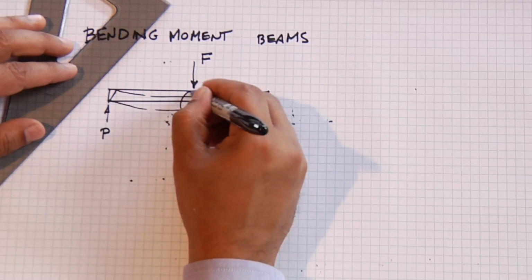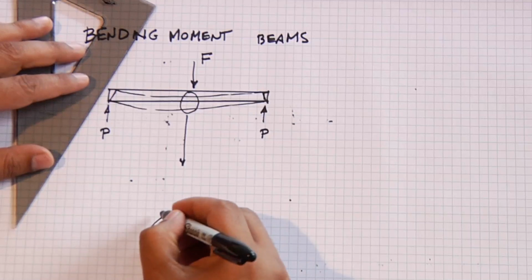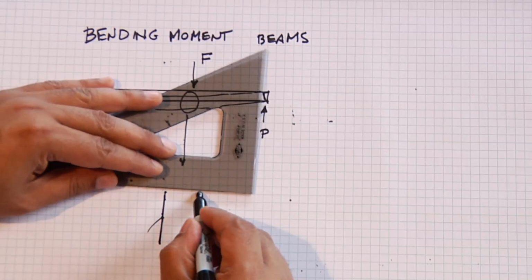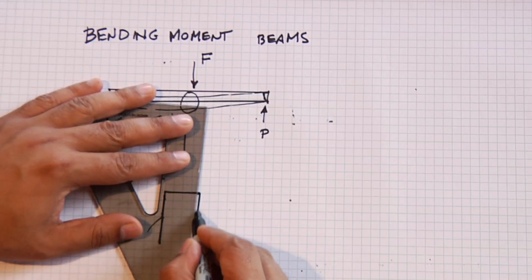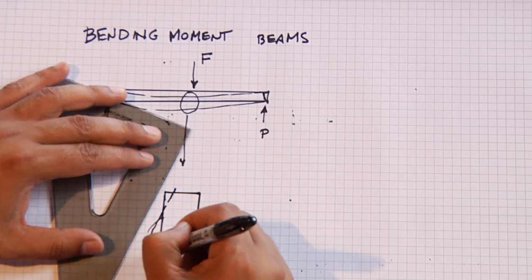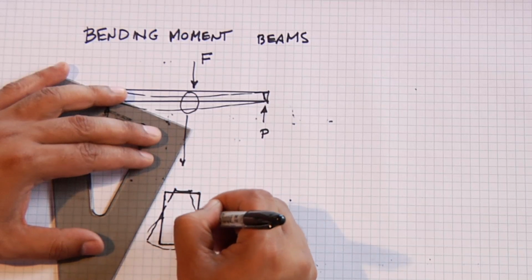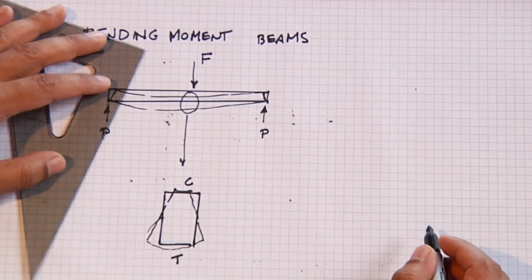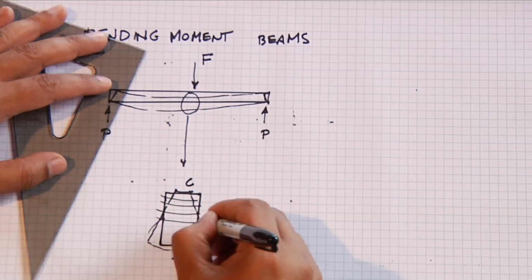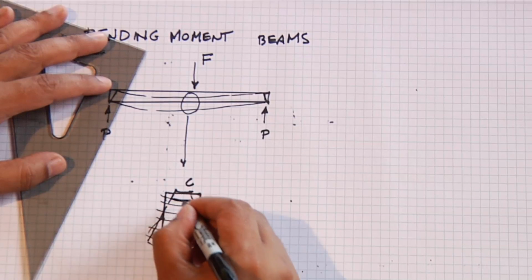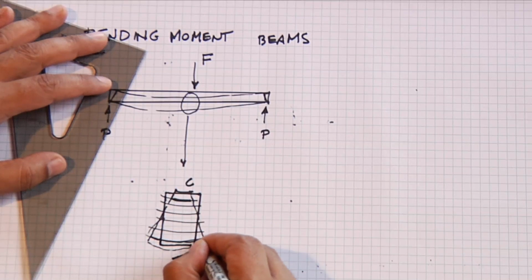And if we took a picture of this and we blew it up, what's happening is the beam element, which started off as a rectangle, is going into bending, where the top part of the beam is going into compression and the bottom part of the beam is going into tension. And so these fibers in the beam are compressing on the top and they're extending on the bottom.